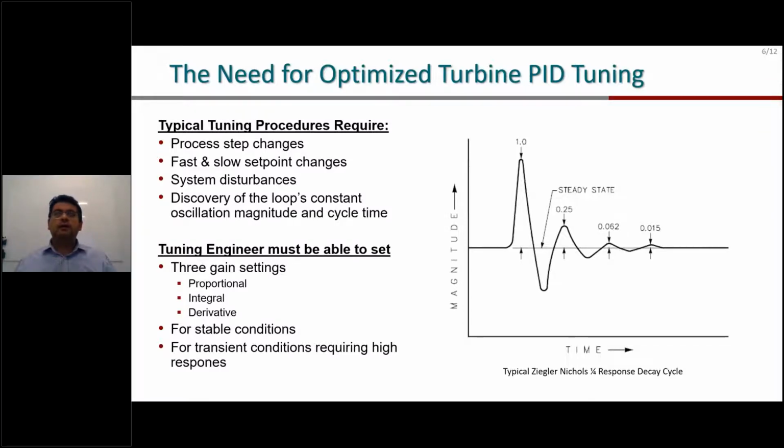For example, some customers have processes where you try to control the kilowatt or the frequency, and the process requirements are very aggressive. So you need to tune your turbine aggressively so that you can achieve that high frequency response of the system. Or you have a pressure or temperature process where you tune it a little bit slower so that you don't have these aggressive responses. Because a lot of aggressive responses within your turbine will cause disturbance and issues within the system.